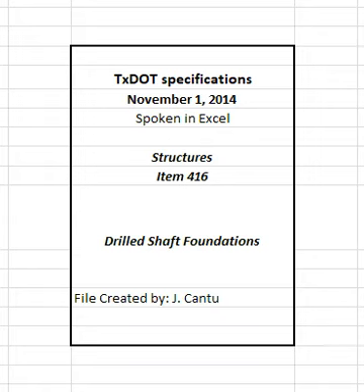4.1.1 Interior bents and piers. Shafts will be measured from a point approximately 6 inches below the finished earthwork elevation at the center of each shaft, unless specific elevations or dimensions are indicated on the plans or unless otherwise directed to meet unusual conditions. The bent height shown on the plans is for estimating purposes only and does not control the top of shaft measurement.